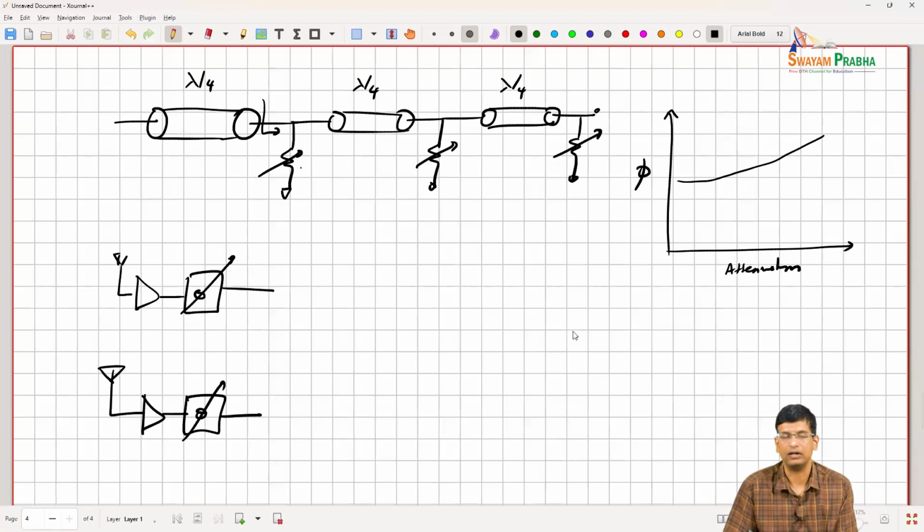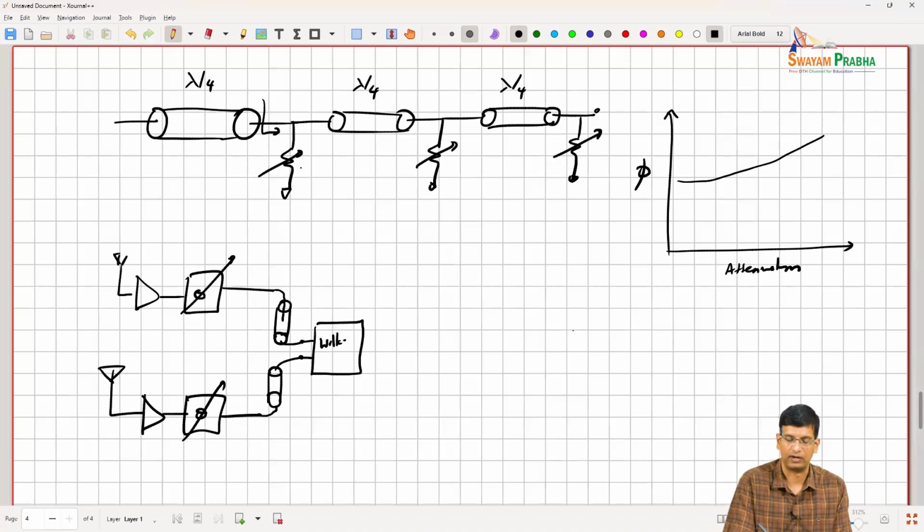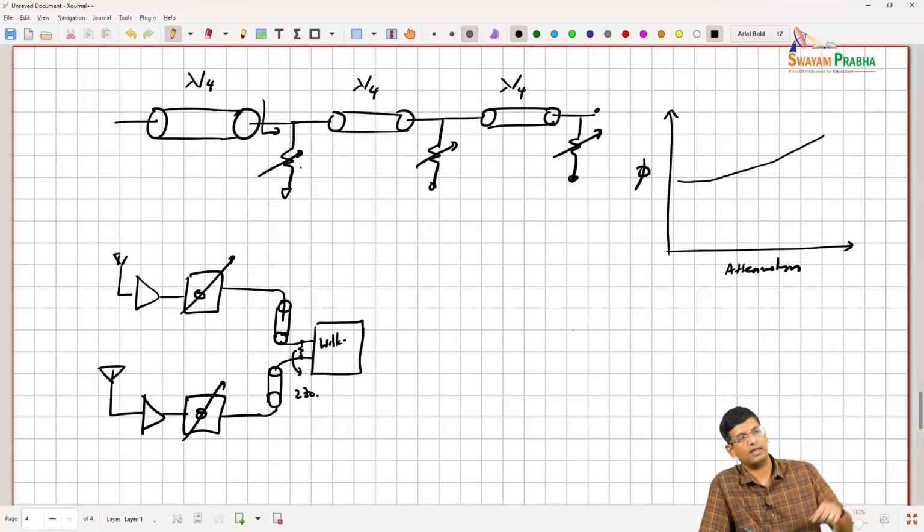So I typically do have this situation where I have to route and usually these lines are long enough that you have to do them with impedance defined transmission lines. But basically you have these long lines that then go to the Wilkinson, right? Because the Wilkinson does need these resistors over here, the 2Z0 resistor to provide isolation, right? And that 2Z0 resistor, you would like it to be right between the inputs. So the Wilkinson does like its inputs to come close together, right?